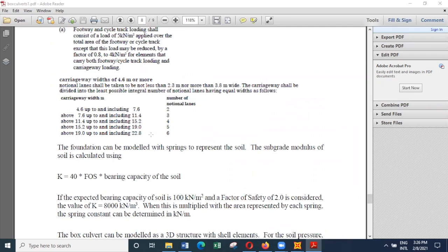So in addition to that, now we have to think about the foundation. The foundation is part of the box culvert, and that is the bottom slab. And the bottom slab is acting like a raft. So because of that, generally we use a thicker slab for the bottom, because it's loaded by 2 walls on the edge, which are almost like rigid walls.